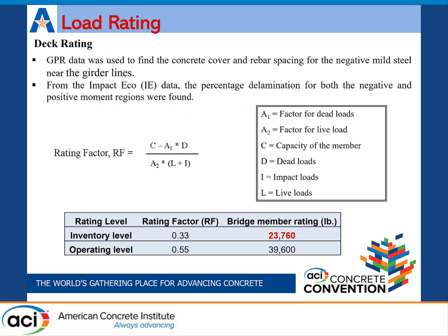Then the deck rating was performed according to the AASHTO Manual for Bridge Evaluation for the HS20 truck. The rating factor equation expresses capacity minus factored dead load, divided by factored live load and impact factor. So how does it work? If the rating factor is more than 1, then the rated element is able to carry the HS20 load, and if it is less than 1, the rated element can't take the HS20 load.